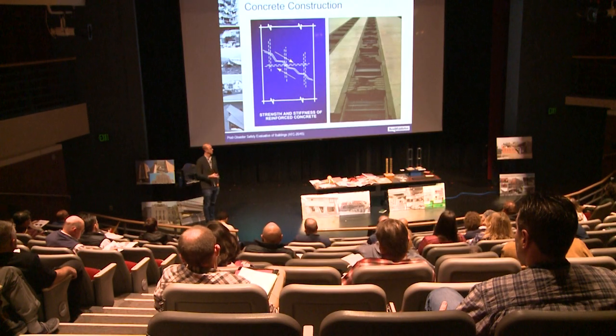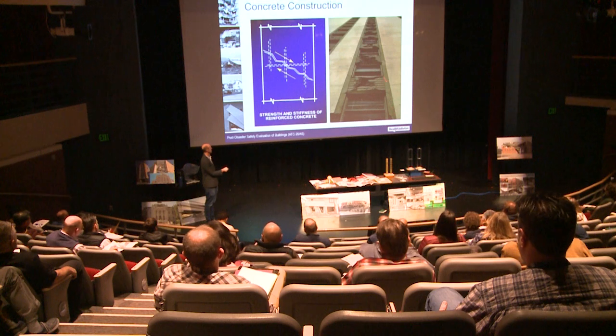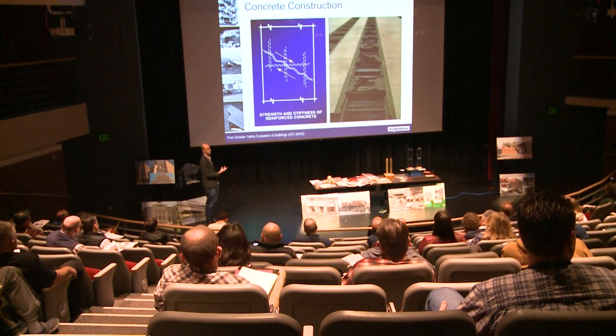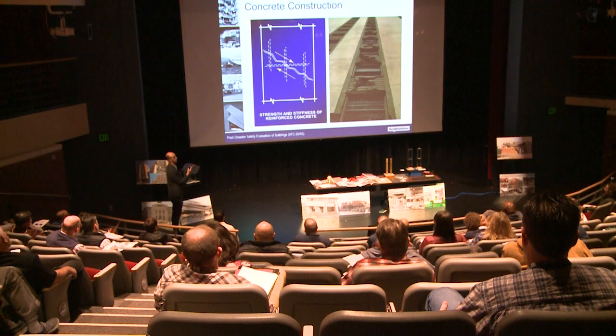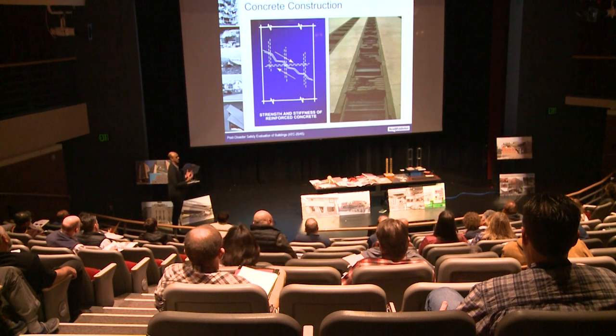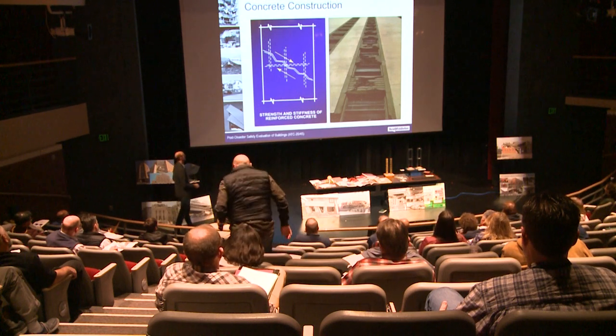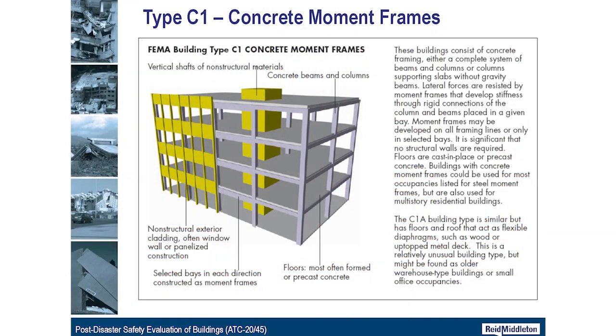And we discussed earlier, we like to see the damage concentrated in the beams or the spandrel or the coupling elements rather than the panels. So this 1964 Alaska earthquake example, to a structural engineer, this is beautiful. Wall piers are perfectly intact, and all the damage was designed so the weak link, the fuse of the system, if you will, are these coupling beams that did a lot of work.